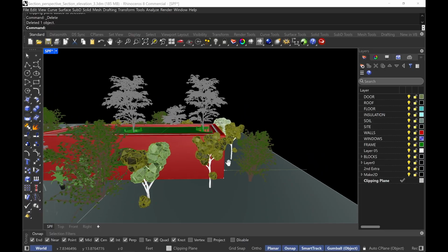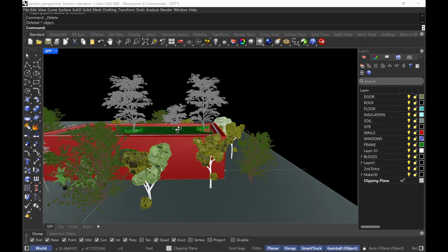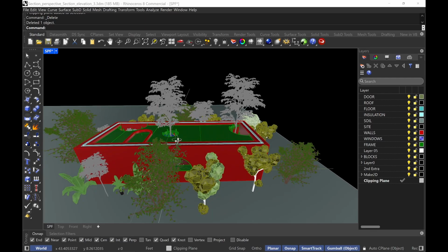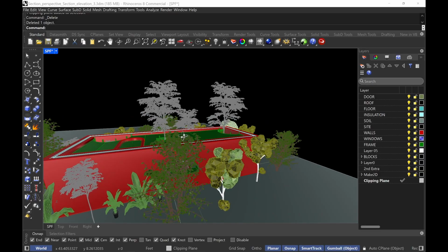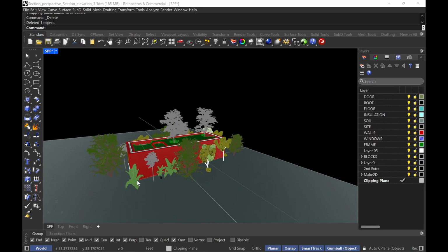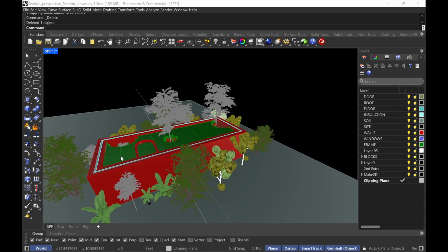Now, number two is that before we actually make the cut and do the clipping plane settings and the perspective section elevation, we want to split what we want to show versus what we don't want to show. And it's actually very simple. So I want half of the drawing to show, or to be more specific, I want half of the elevation to show right here, whatever the front face is. So I don't have to worry about anything else. We're not going to split the entire model in half. We're just going to split the most foreground geometry.